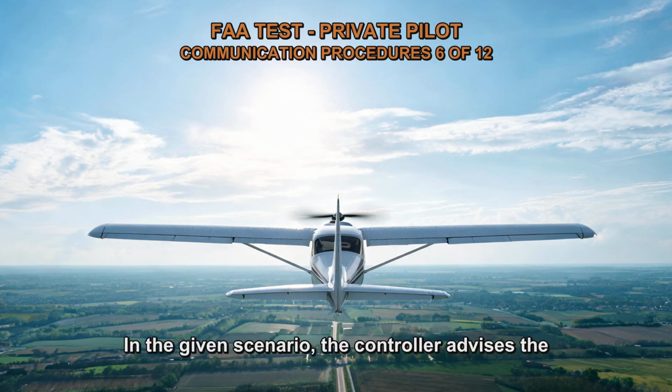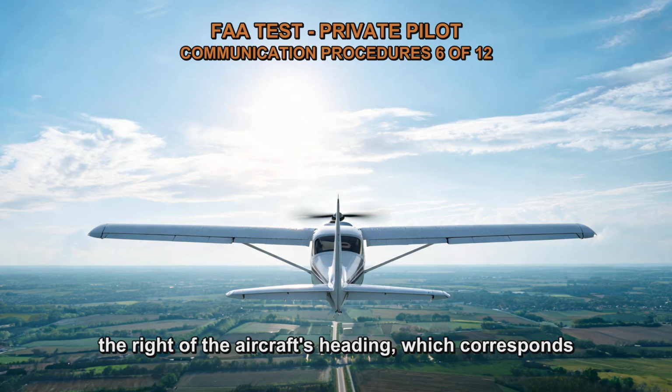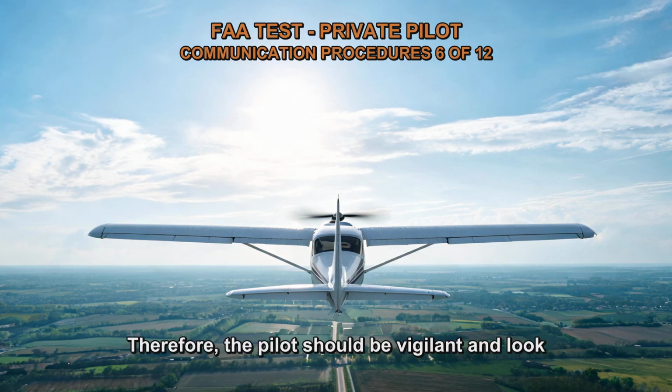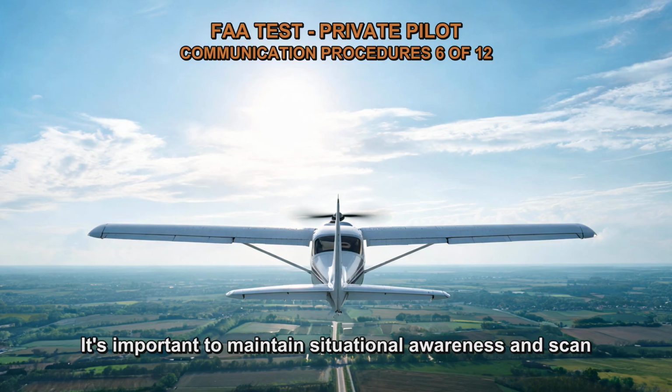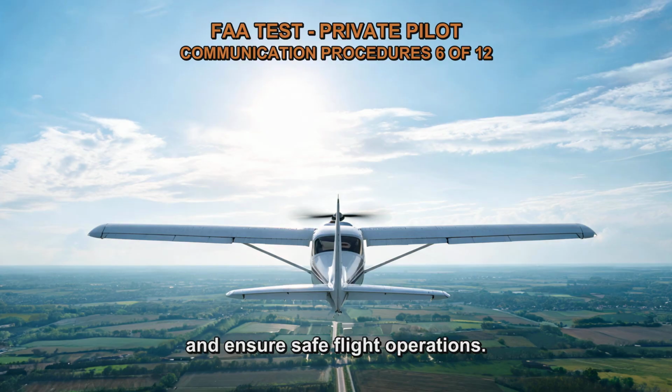In the given scenario, the controller advises the pilot of traffic at 3 o'clock. Since the pilot is flying on a heading of 090 degrees east, the 3 o'clock position would be to the right of the aircraft's heading, which corresponds to the south direction. Therefore, the pilot should be vigilant and look towards the south to spot the traffic mentioned by ATC. It's important to maintain situational awareness and scan the sky for the traffic to maintain separation and ensure safe flight operations.